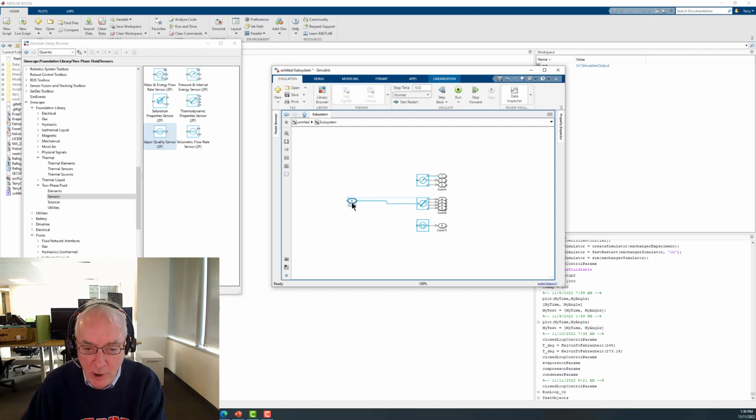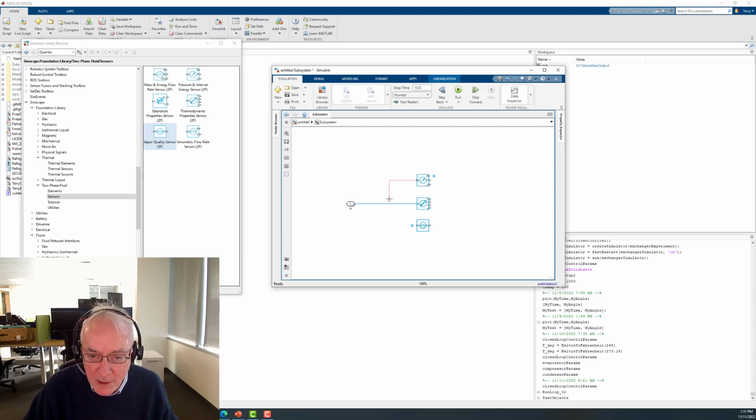And it's going to basically be a probe, and that probe connection to whatever fluid node we want will set these calculations, all right? And so I'm going to just call it A, because A is simple, right? And none of these presumed outputs or interface setups are going to be used. So let's get rid of all of them, right? But again, it's a probe that's going to measure pressure and internal energy, and so I can connect all these into A. All right, so now let's make it big enough so we can see things well. Let's move that down.